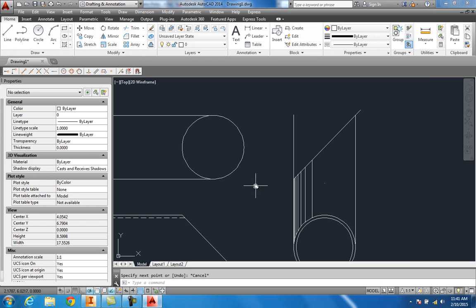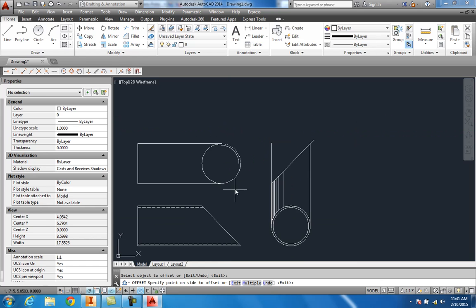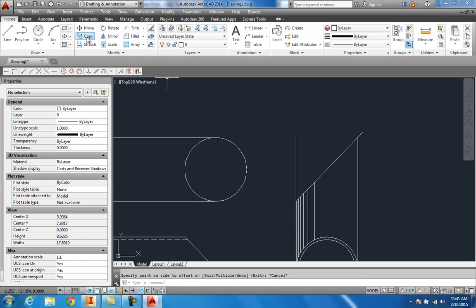But also on this thing here too, I'm just going to hit offset 0.125, enter, and you see it's only doing, and I'm making that interior look about the thickness of the material. What you'd want to do is go to PE, Polyline Edit, click on this line, and hit Join. I want to join all these together and make it one entity.